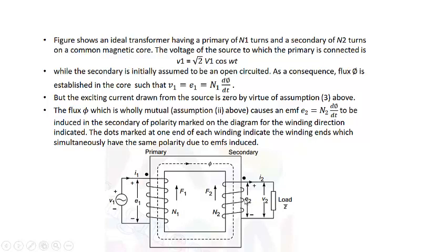And we know that a source of power, when it supplies the current, supplies it from the positive terminal, and it returns to the negative terminal. So this is what is meant by the dot. And I told you that if this is the positive polarity over here, this will be the positive polarity over here, because their polarity will be the same and they are marked as dot. And dot polarity marking means whenever the current enters at the first dot, the current leaves at the second dot. And the same polarity applies to the induced EMFs. That is what I have just described.